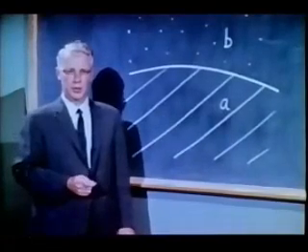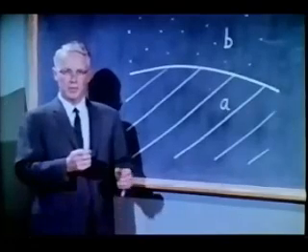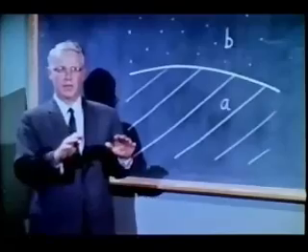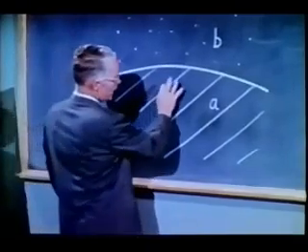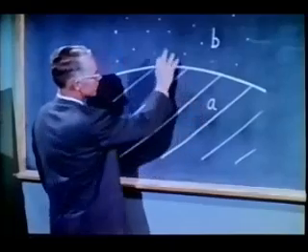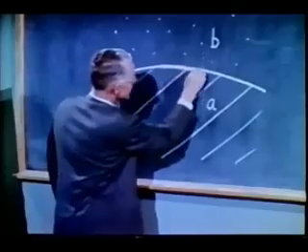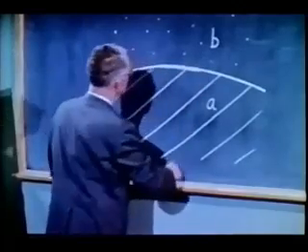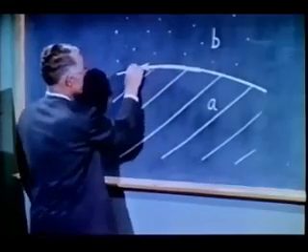Surface forces lead to a third boundary condition that should be used with the equations of fluid mechanics. If the surface tension varies along a surface, then the surface must move. Consider a boundary between a liquid A and another fluid, such as a gas B. Think of a unit length of the boundary and the forces acting on it. It will be pulled in this direction by surface tension, and it may be pulled in the other direction by a slightly larger surface tension.